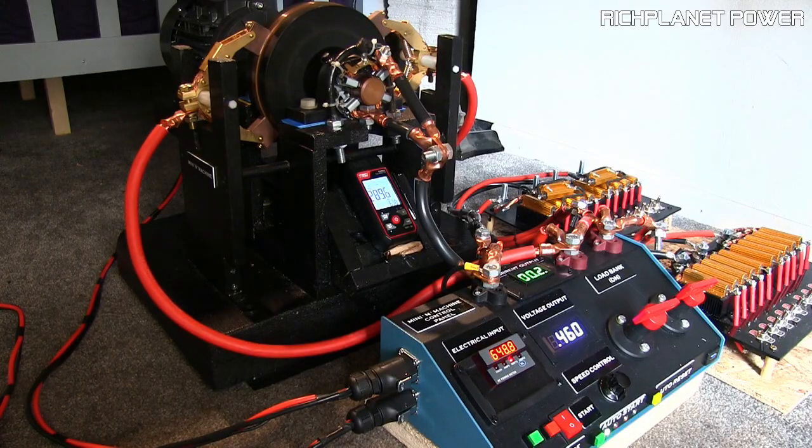Using metal liquid contact will also reduce the frictional force of the brush on the disc, thus minimizing frictional losses. In my opinion, from my results and looking at De Palma's results, it can only work by using liquid metal contacts within the machine. And this is exactly what both Trombley and De Palma were striving for in their later machines. De Palma used mercury and Trombley used sodium potassium eutectic known as NaK78.